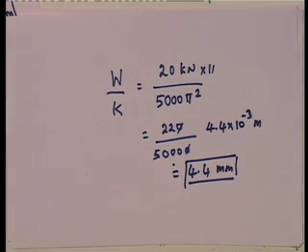So, when we were talking about requiring soft springs, I was saying that sometimes soft springs cannot be provided. I went through the computations to show you that even to get a transmissibility ratio of 1/10, which is like 0.2 kilonewton when you have a 2 kilonewton force, it's practically negligible.